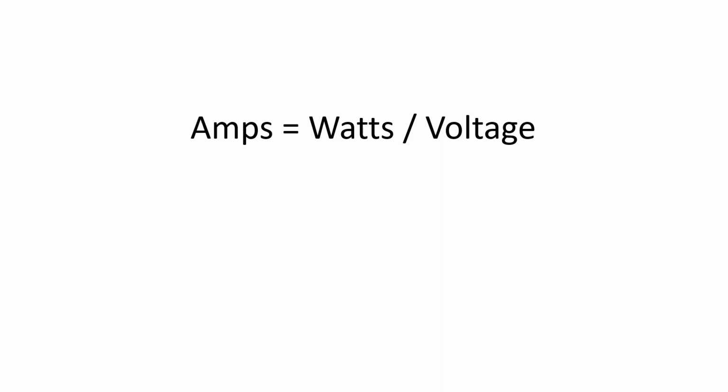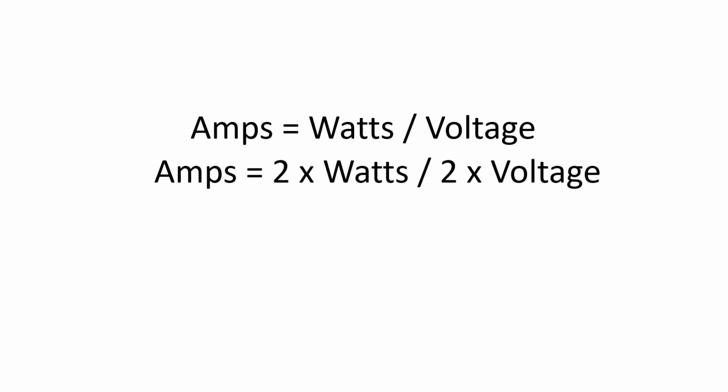If you go back to our equation to calculate the amperage, you take the watts of the light divided by the voltage. We have doubled the number of lights, but we've also doubled the voltage. So yeah, you're pulling 2 lights of electricity across this wire, but by doubling the voltage, you are cutting the number of amps in half. Basically, using 240 volts between the wires reduces your amperage on each light. So essentially, you're left with 1 light's worth of amperage flowing through this wire. So our calculation for the voltage drop in this hot A is still valid.